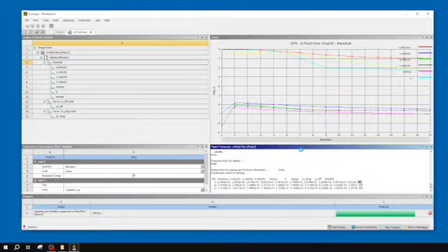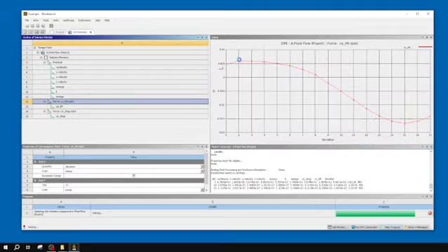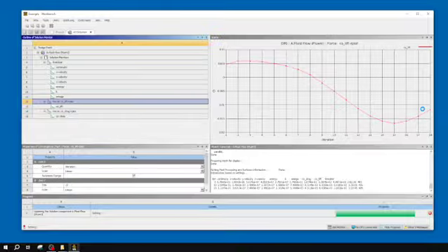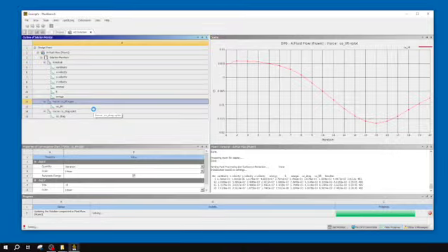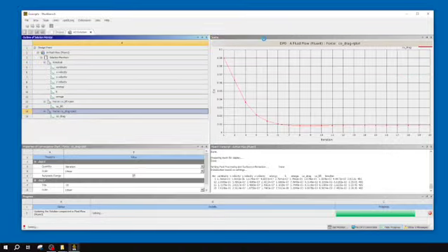If I flip over to my lift, we can see our lift being plotted. This is a symmetric airfoil that I'm simulating, so I'm expecting small numbers, hopefully something close to zero, right? We're at 0.005. We seem to be moving back up to zero. It might oscillate a little bit, but we'll check in on it closer to when it's finished. And finally for drag, we can see it drops down, finds what it is. Most of this is drag due to the surface of the wing.